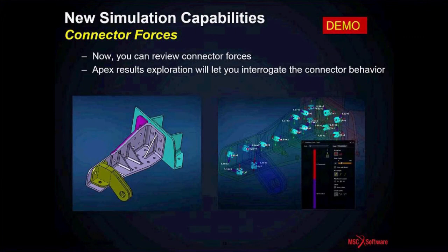Connective forces. In any engineering simulation, what is important are two things, in my opinion: looking at the cross-section forces and looking at the connective forces. Once we are able to explore those forces in the connections in the model, one can make an engineering judgment whether the fasteners in that model are adequate, and whether the size and the shape of the fasteners are okay, it could be a bolt or it could be weld, etc., and how we can quickly interrogate those results in Grizzly.